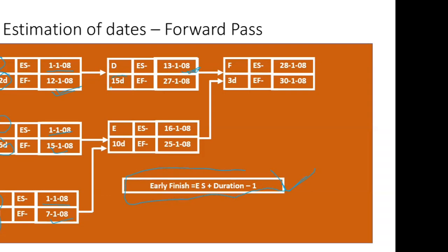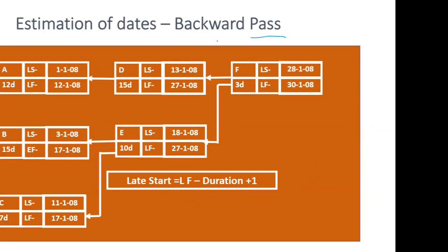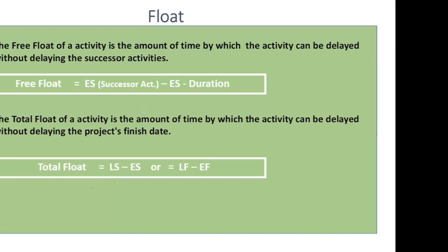And similarly, again, you have duration. So with the help of duration and this early start, you can get the early finish, right? And this is how you will prepare a forward pass for your activity, right? Similarly, this is how the backward pass will work.